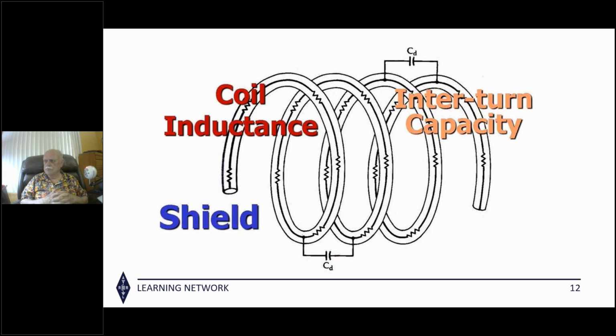Next, where is the separation between high HF and low HF related to the ferrite filter? That one I'd have to do a little research on to give you a quantitative answer, because ferrites are operating in loss mode when they're used as a balun, and I think the answer to that question can partly be found on Amidon's, Bill Amidon's website, amidon.com. You've got to look at the characteristic curves of the ferrite to see where the loss range is, where the ferrite has a kind of rounded curve showing its efficiency and inefficiencies, and you want the ferrite to be inefficient on the frequencies you're operating on. That's a complex question, which we could try to answer in a later session. I do have a presentation on that one, by the way.